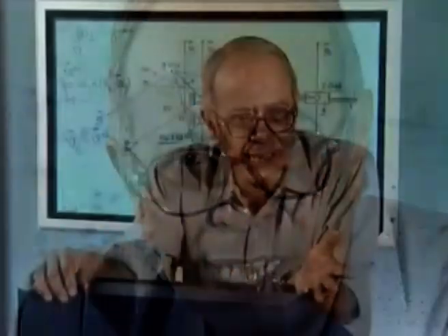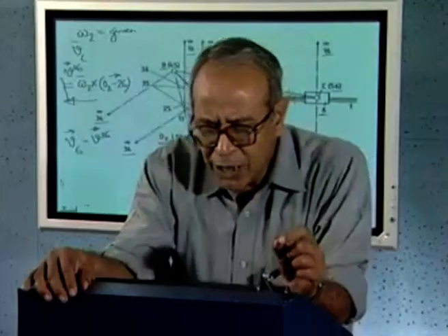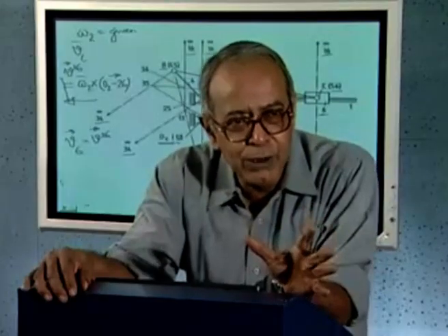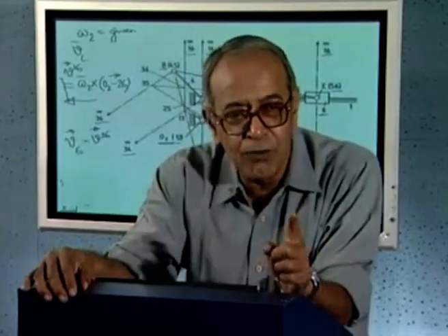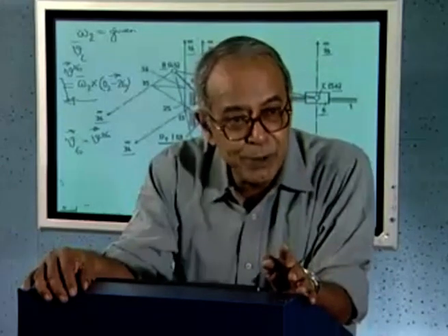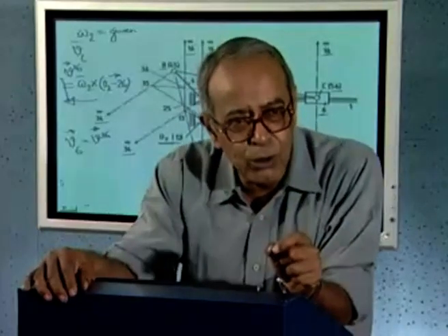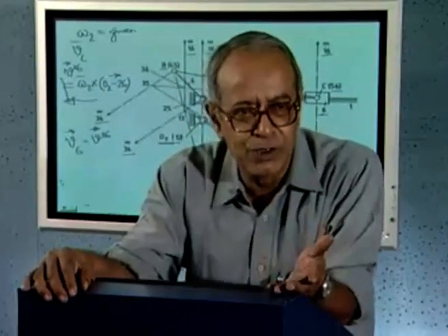Once we have determined all the relative instantaneous centers, I have also explained how we can use the location of these relative instantaneous centers for the purpose of velocity analysis. That is, given the input velocity, we can find the velocity characteristics of all other links present in the mechanism. One thing we can remember, in the last example we saw that the output link was a slider. So the velocity of all the points of a slider is the same, because it is in pure translation. That fact was very cleverly utilized to find out the output velocity when the input velocity was prescribed.